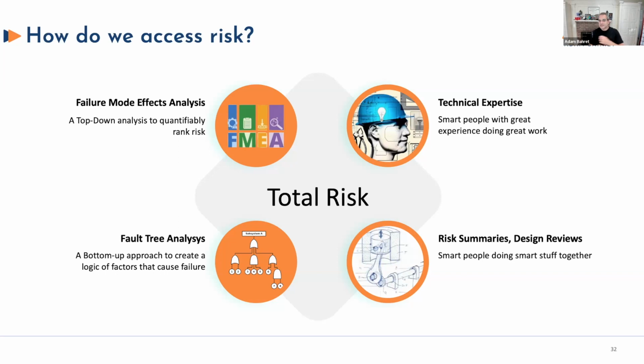Technical expertise, this is design reviews and getting those technical experts to come together and share from their cumulative lifelong knowledge and passion on a specific discipline to share the risks they have together. And the FMEA facilitates this, but you also should do a better job of capturing that in design reviews. I've been in a lot of design reviews and seen incredibly valuable points made, discussions that just get mentioned and they're never talked about again. They were never documented. Then I see an FMEA at a later date and I'm like, how was that not brought up, that came up in the design review? Everybody forgot about it. So that part's really about being diligent and capturing that as the experts share their thoughts.